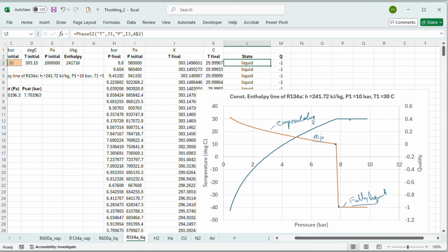What actually happens in real refrigerants is that it's a mixture that goes in, okay, somewhere here, and then it drops further, just like a liquid going in. So if you started here too, it will drop significantly. So that's not exactly Joule-Thomson expansion of gases. That's more like expansion happening in an expansion device. All I'm trying to tell you is the drop in temperature happens in the expansion device.